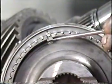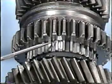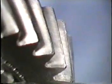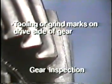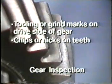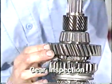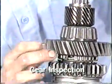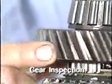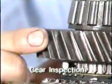Since the T50D doesn't have alignment marks on the synchro assemblies, you would paint marks on the ring and coupling sleeve before disassembly. When inspecting gears, you should look for tooling or grind marks on the drive side of the gear, chips or nicks on teeth, and abnormal contact patterns. Tooling or factory repair grind marks on tooth surfaces are normal, but chips or nicks in teeth or abnormal contact patterns should be examined closely to see if they're within acceptable limits.